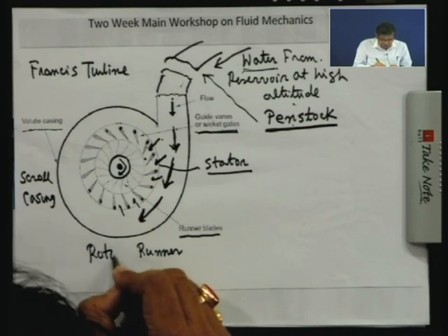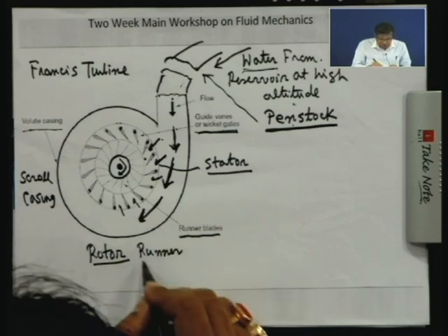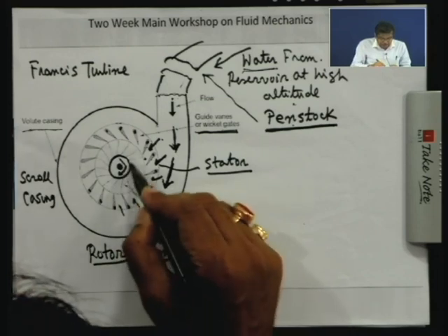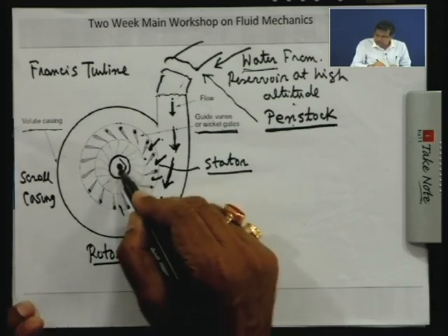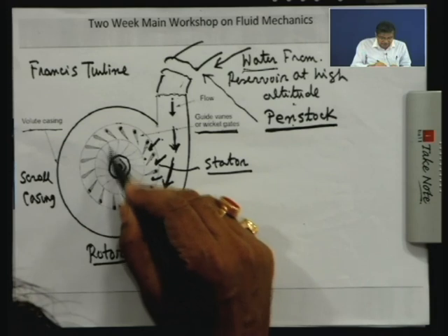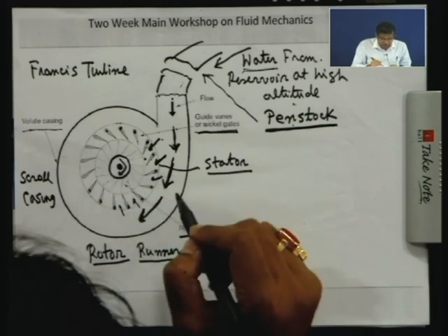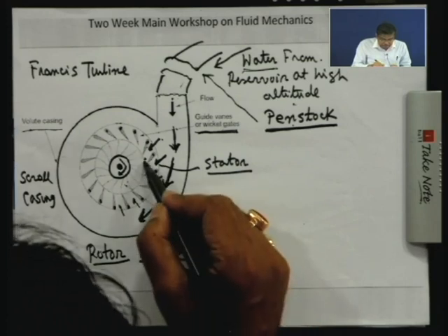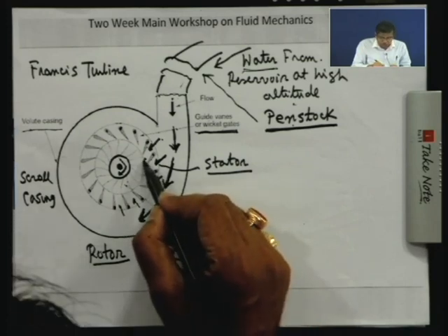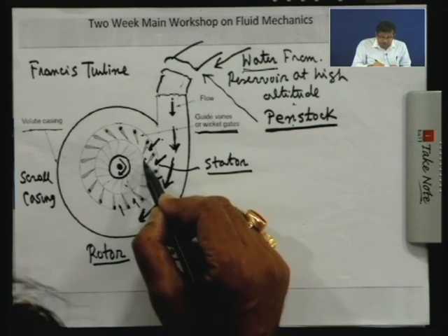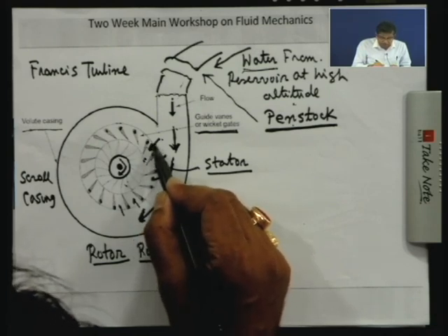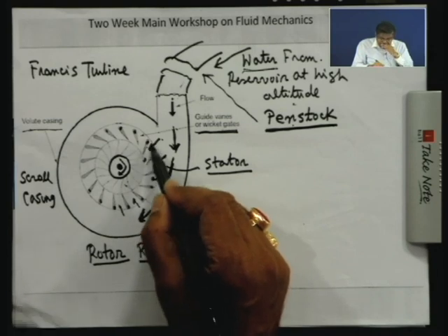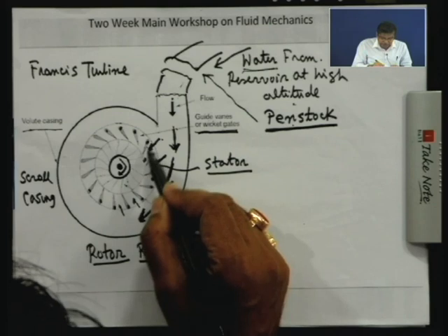The rotor of the machine, which is the moving part that rotates, is known as the runner, which consists of a disc mounted on the shaft, and on the disc there are radial vanes mounted. These blades are known as runner blades. Now, when the fluid enters the runner blade, it has both pressure and velocity, because some high velocity is generated by the conversion of pressure energy to kinetic energy while the fluid flows through the guide vanes, the stationary blade passages.